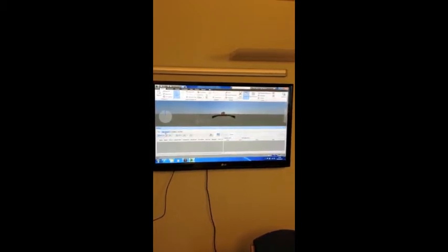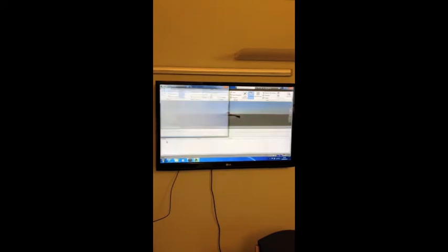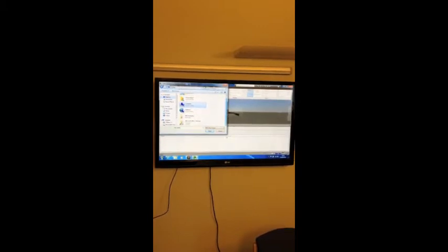So you go onto Data Sources and Add. And then you click on Microsoft Project MPX. Then go to where you've saved your ASTA programme as an MPX file.